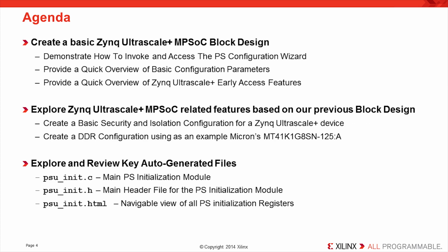www.xilinx.com. For our agenda today, we will start by demonstrating how to access and invoke the PS configuration wizard for Zynq Ultrascale Plus MPSoC. We will then provide a quick overview of the basic configuration parameters before we highlight some of the new features introduced specifically for the Zynq Ultrascale Plus MPSoC family of devices. The two new features we will be focusing on are the system security and DDR configuration.